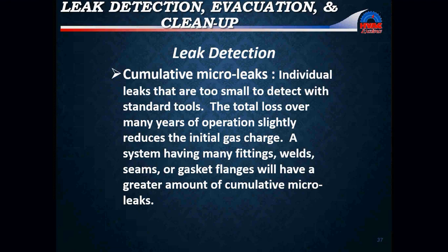the reasons. Oil is always present on Schrader valves and access ports due to the discharging of refrigerant hoses on the manifold and gauge sets. These parts are often falsely blamed as the main point of leakage. You got to put your gauges on them to see what the pressures are. So you're going to have oily residue around those areas, around your service valves and access ports.